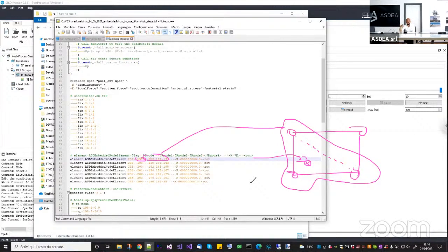That's why I'm saying you don't need to actually do a mesh with triangles, because here I do not pass the tag of an element. I pass the tag of three nodes. So they can be the three nodes of a real triangle, or three nodes of a quadrilateral, or three nodes of a 9-node element, for example. Okay.